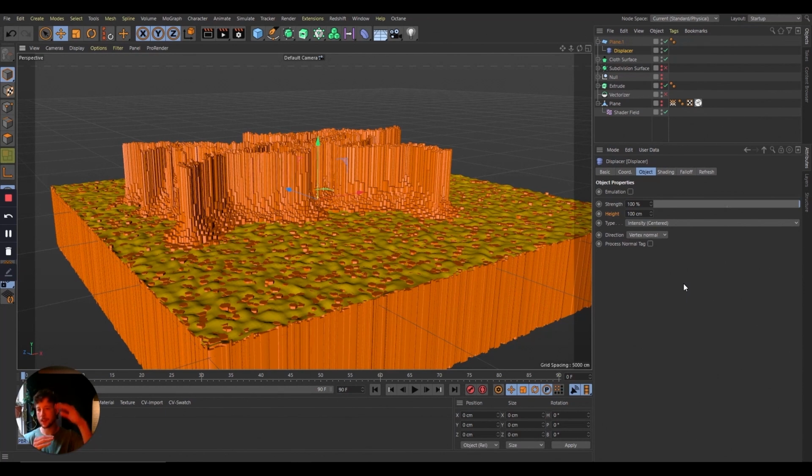It's just a grayscale image determining a low point and a high point from black to white. So if you wanted really realistic sand dunes, maybe you could find a really nice satellite height map of actual dunes, and you can get that really nice randomness that maybe you can't necessarily achieve so quickly with noise shaders and stuff like that.